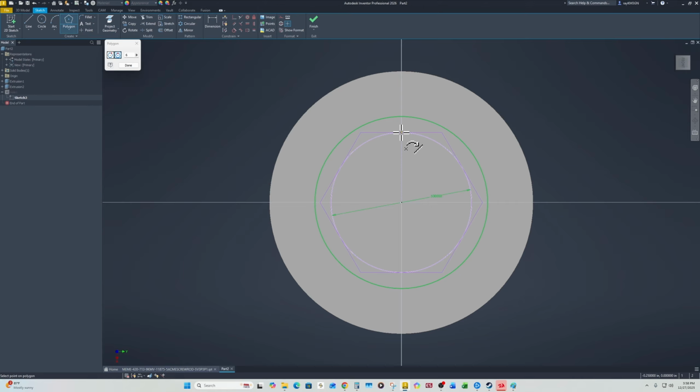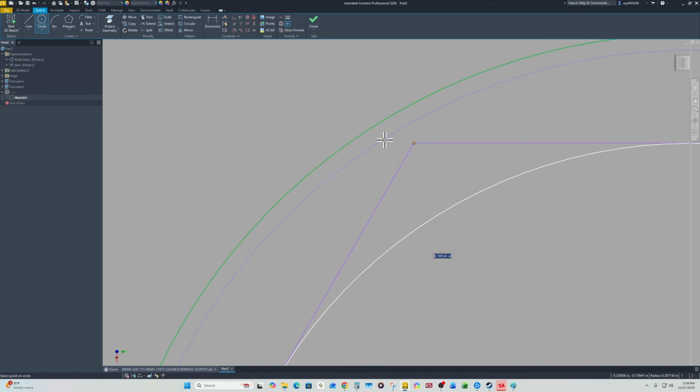And then once it locks in, I just click it. You should be good. And now the information that we need is just the diameter big enough to clear this section right here, the point of the angle. So the minimum diameter that we need is 0.577350. We're just going to choose a standard dimension. So 0.577. The size below that would be 0.5625.